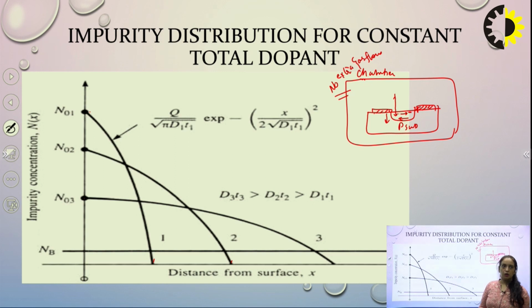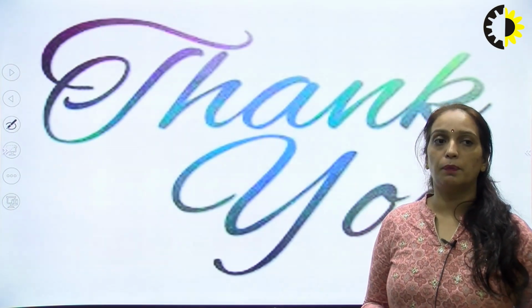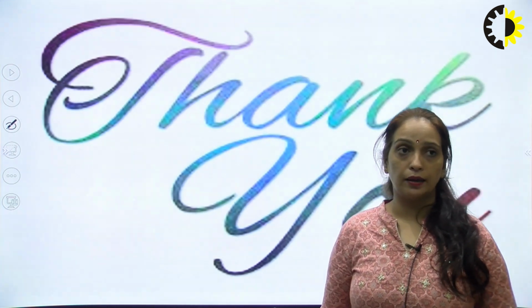So today we are going to stop here, and finally we can conclude that the diffusion process is not a single process, it is a two-step process. First we have the pre-deposition, a layer of gases will be deposited there, and that layer will be diffused inside the surface during the drive-in process. So we have learned about the diffusion, how the diffusion is done, how it is dependent on the crystal structure, and what is the basic difference from ion implantation. In the upcoming slides, we are going to see the reactors which we are going to use, and how the ion implantation is done.